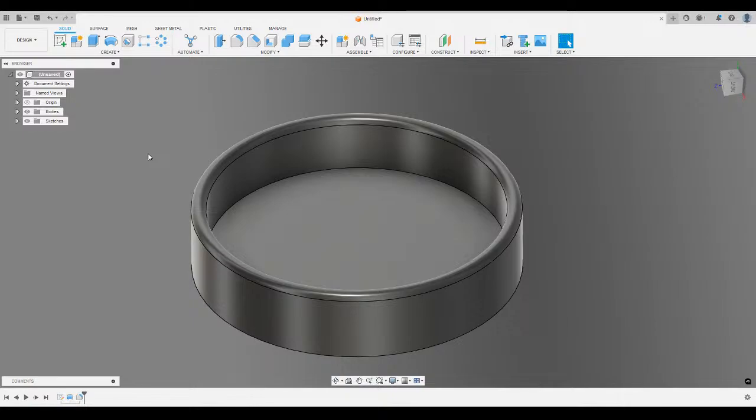And again, you're just going to get a stronger part because you're not going to have a concentration point for stresses. For clarity, what we're talking about is a fillet that has rounded the edge over, as you did in your initial sketch with the cube when you were first showing fillets. That happened on the X and Y axis, but it actually benefits the walls going up on a part that's being designed in the Z axis as it's being printed.